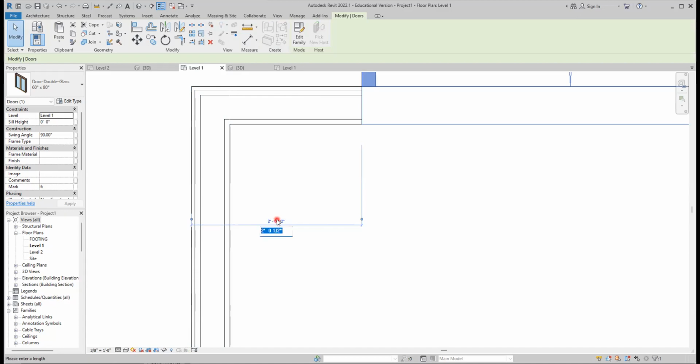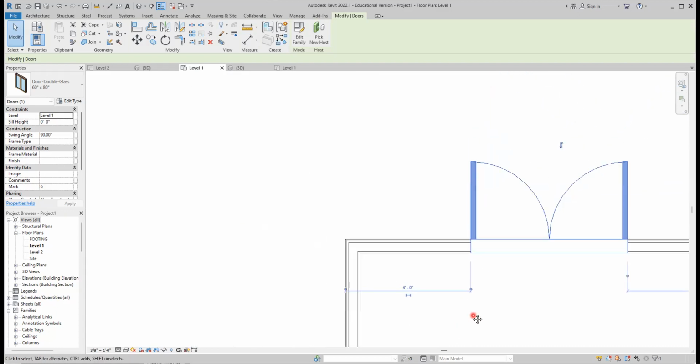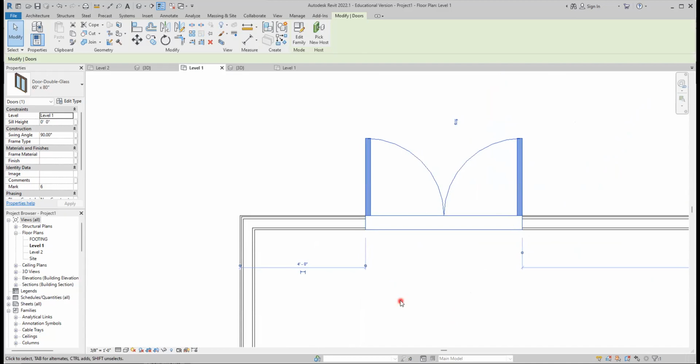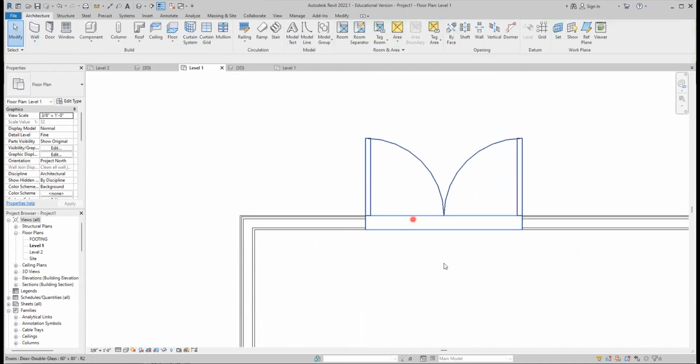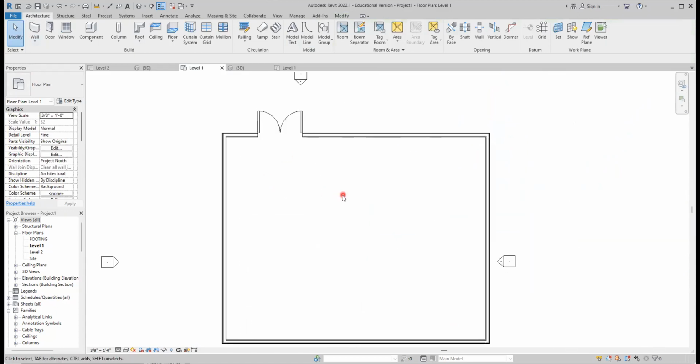Now, the distance that I want to put in is right here. I'm going to click right on this. I'm going to type in 4 for 4 feet and press enter. Now I do that, it goes ahead and puts it over like that. So that's in place right now. That is perfectly in place. Now, once it's in place, we click on the modify arrow to get out of there. So far, so good.